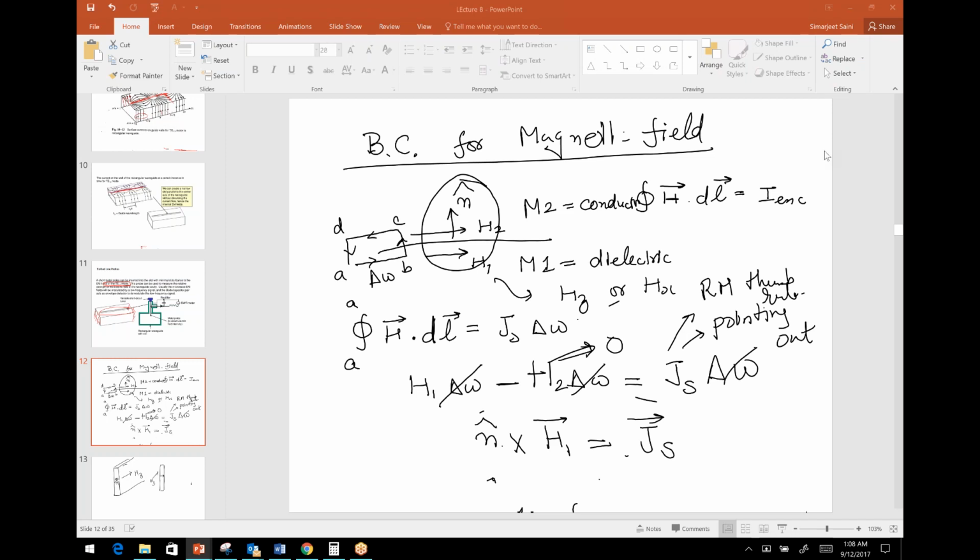Basically, the idea is that the gold conductivity doesn't drop as you go to high frequencies. So you put a thin layer of gold, basically above the skin depth, which is half a micron or so. So you put a very thin layer of gold on top.